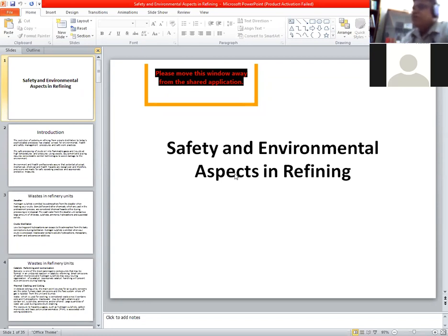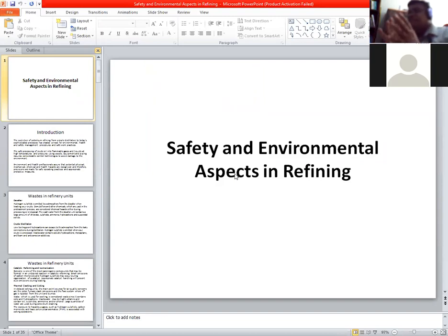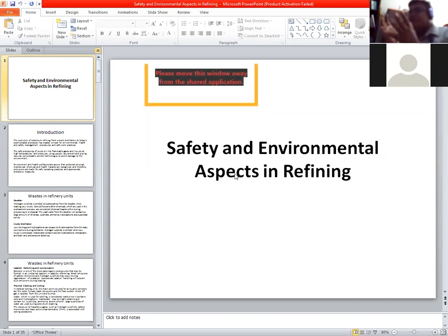Safety issues also we have to be concerned about, because in a petroleum refinery, a lot of pressurized equipment is used and lots of flanges. Flanges means the connections. A lot of pipeline connections are there. So if there is a very poor connection on pressurized equipment, the hydrocarbon, especially low boiling temperature hydrocarbon, may escape, and it is very common.